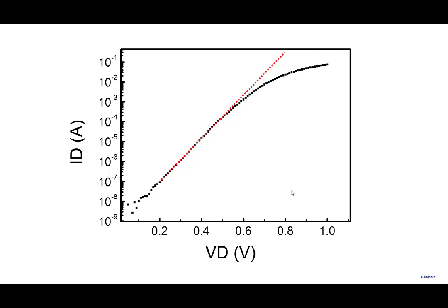The voltage at this point is 1 volt. So your diode can sustain 1 volt, can sustain 1.1 volt. But what is happening is the characteristics are no longer exponential. As you go to higher and higher biases, they depart from the exponential nature that you expect. Here it is nicely exponential, here it is not.